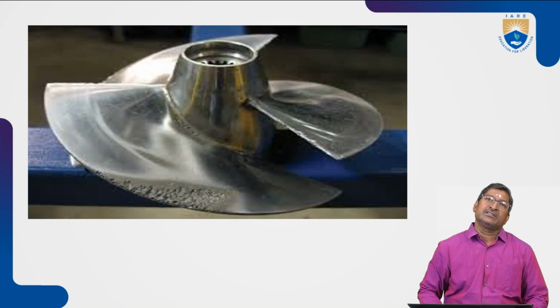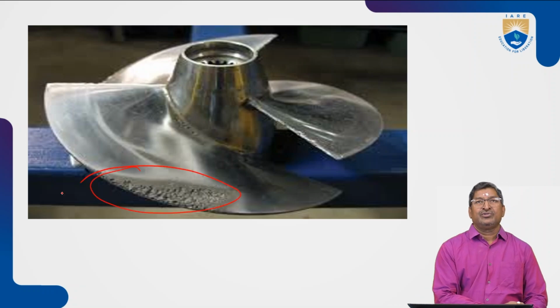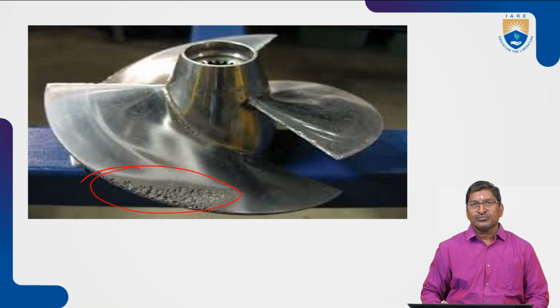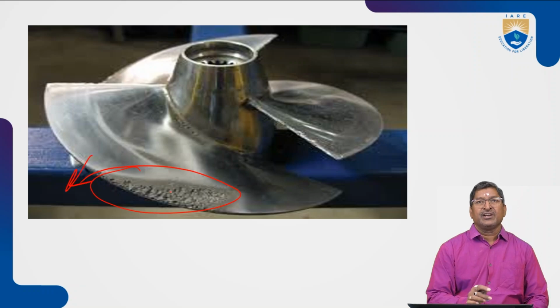You can see this impeller, this is the damage due to cavitation. Water is flowing like this, that's why damage occurs on this side.